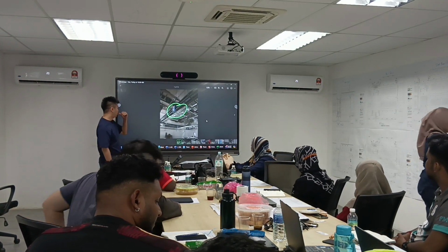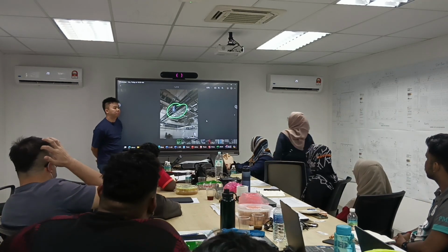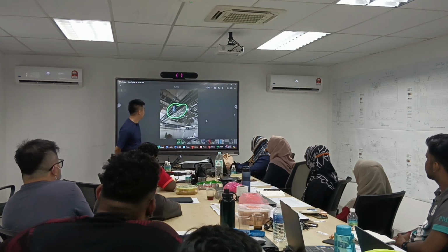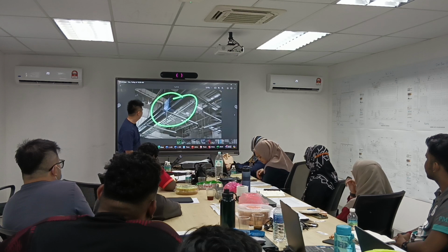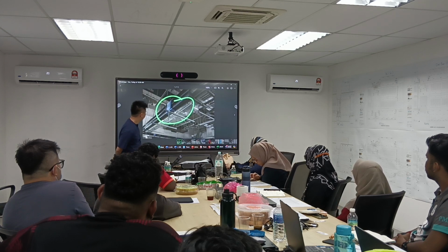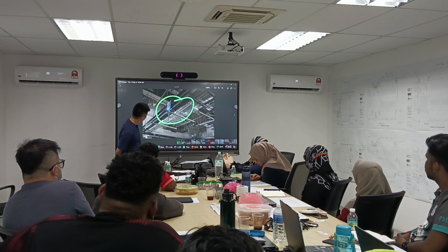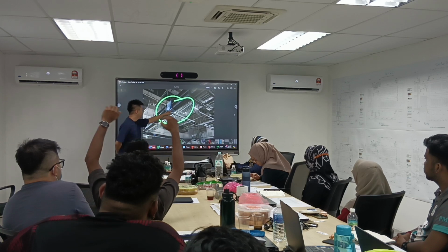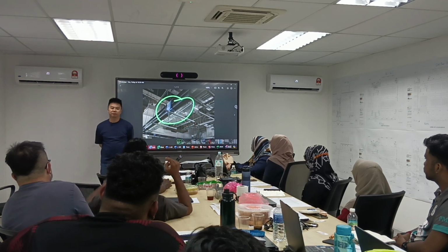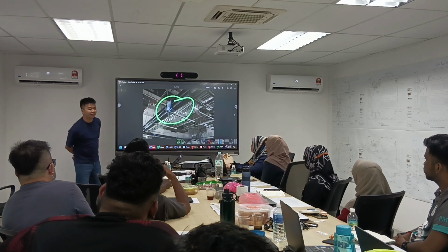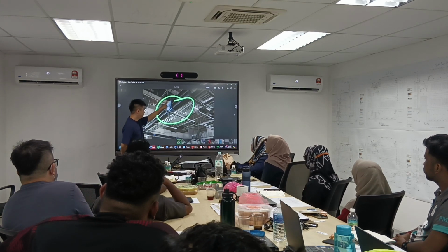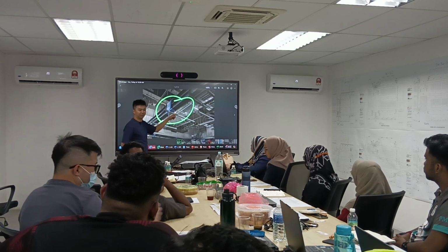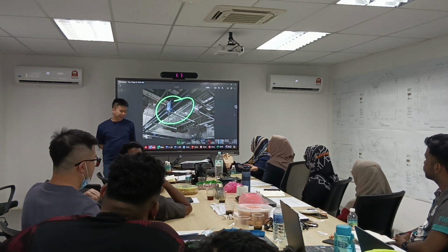In this photo, quality issues, what do you see? The T&C team circled this. What does this mean? The support is not supposed to be there. Why is the support not supposed to sit here? Correct, because this box is where you're going to service. You need to dismantle this box. If your support sits here, in the future, how do you dismantle the box? Okay, not bad.